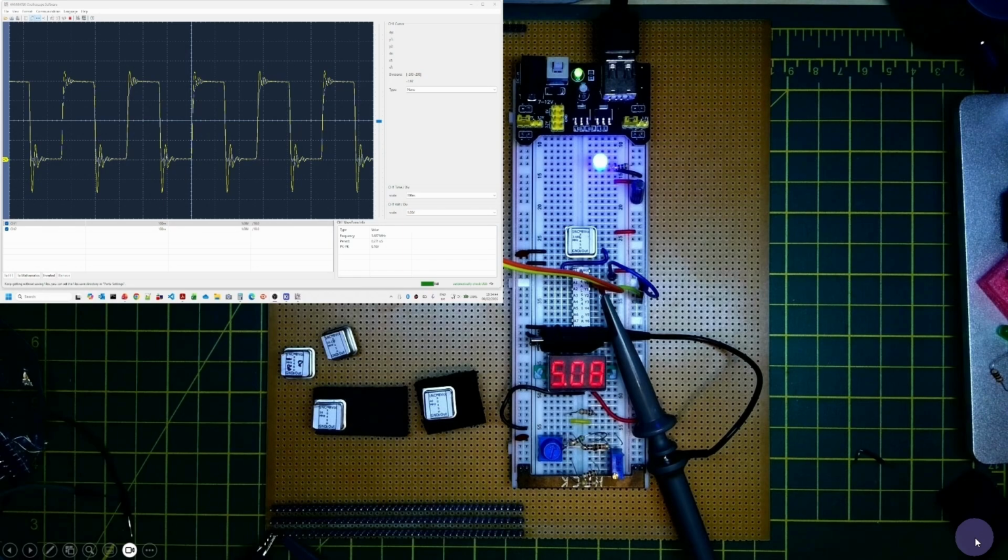Welcome to Breadboarding. In the previous video, we looked at the AND, OR, and exclusive OR logic gates, and we also looked at a buffer here, which is used to boost the signals to go along bus rails. So we had this strip board bus rails that I've used in the earlier series. And we also connected one of the oscilloscope probes down the end of this, and you can see here the wire from the output of this crystal oscillator is going all the way up to the top of the board here and then down these rails.